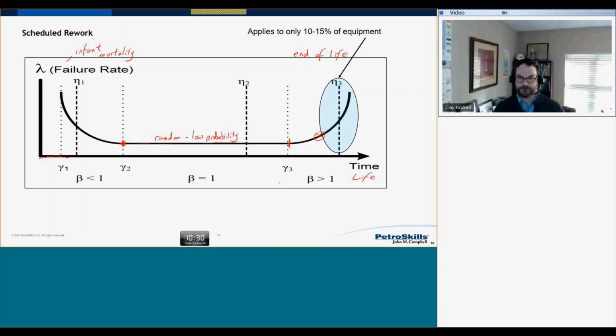So you put new bearings in, you put new seals in, you check the wear rings. If there's signs of cavitation, you change the impeller and so on. It means perhaps somewhere around about here, at that time here, that's when we've overhauled the bearing. We've overhauled the pump. And it means you never actually see this bit.